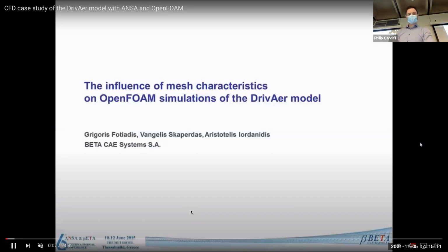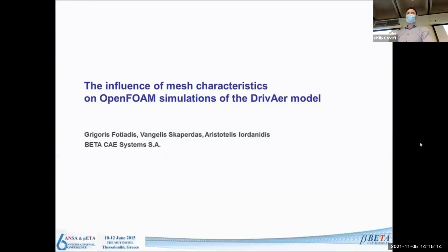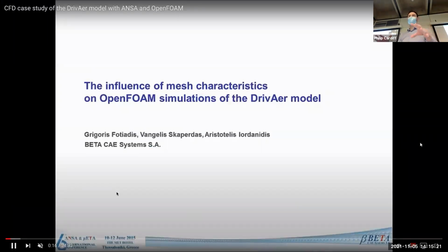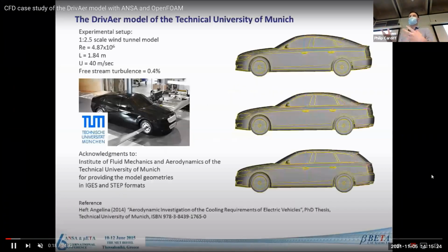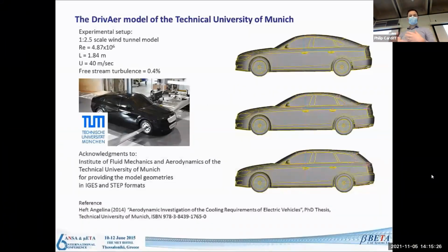The DrivAer case was like an experimental benchmark for automotive companies for CFD models. They basically took, I don't know what it was, like a 3 Series BMW, and then they instrumented it, set it up in the wind tunnel, and measured everything very precisely. Then that's published openly, and they publish all the results. So if you want to benchmark your CFD code, they've described it fully. You can set up the full wind tunnel model and compare turbulence models, RANS approaches, LES approaches, DES approaches, to see how close you can get to the lift and the drag.